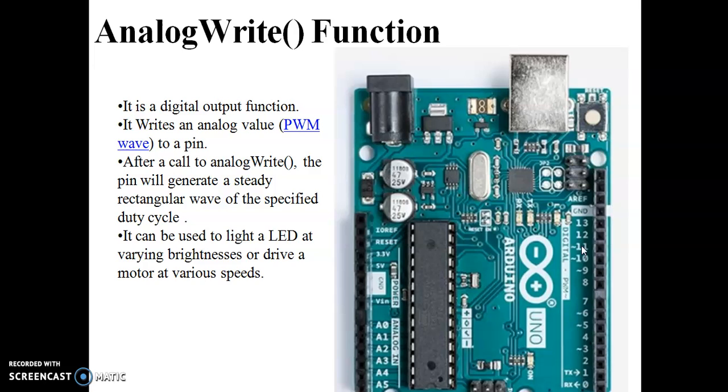If we carefully observe D0 to D13, we see the difference that on the PWM pins there is a tilde symbol. It indicates that these are the PWM pins.